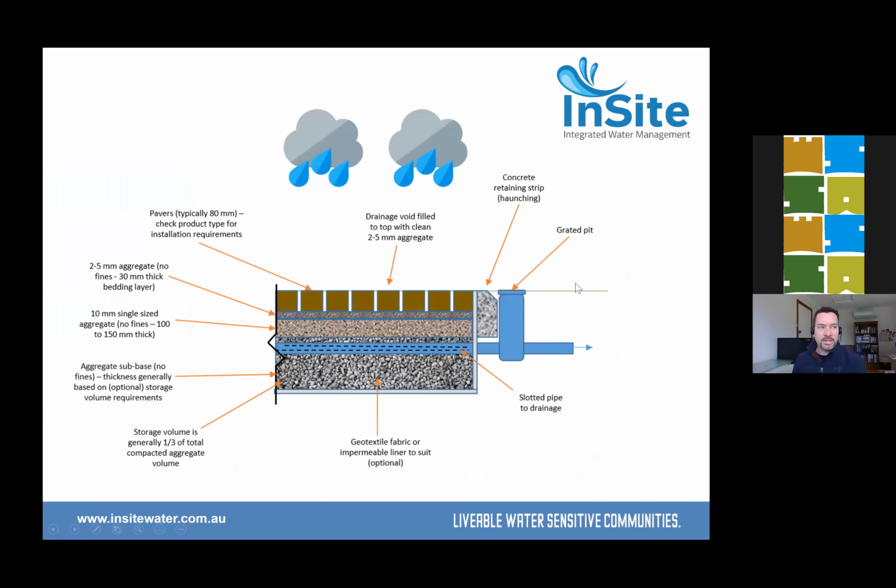A less traditional on-site detention is that you can actually engineer gravel storage, maybe even up to a 1 in 5 year storm under pervious paving. Pervious paving also reduces OSD requirement because it reduces the area of imperviousness directly connected to council drainage systems. So you're effectively improving the post-development runoff coefficient of a site by installing pervious paving.